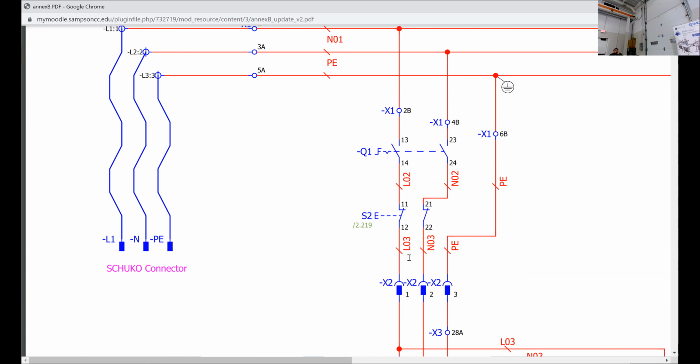The E-stop, when you release the E-stop, the contacts are closed, normally closed. Now look, when you hit the E-stop and you slap it like this, the contacts open. So that's the difference between an E-stop and a power switch. Power switch is normally open, E-stop is normally closed. That E-stop lets it run until you hit it. It's an easy way for them to go up to something, bam, hit it, and it's going to knock it out. It's like a panic button on the front.